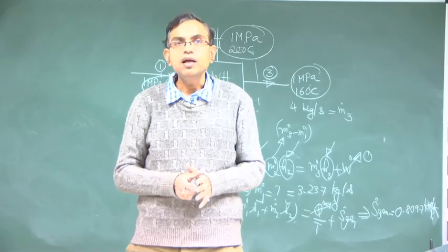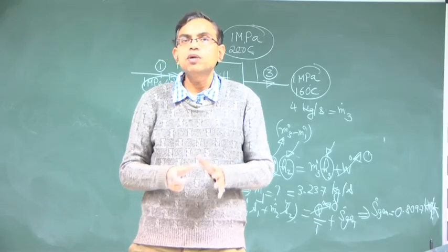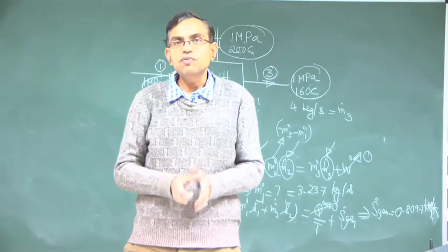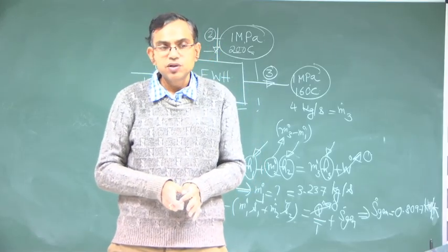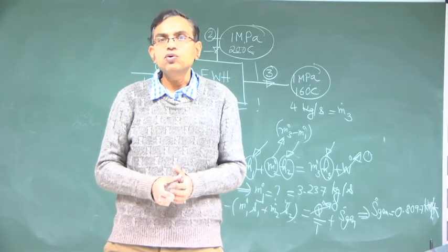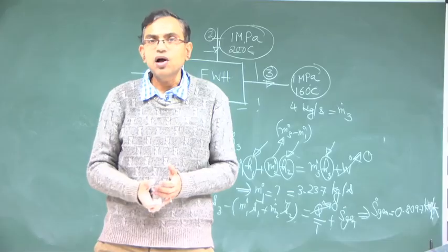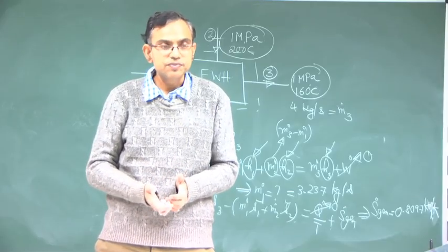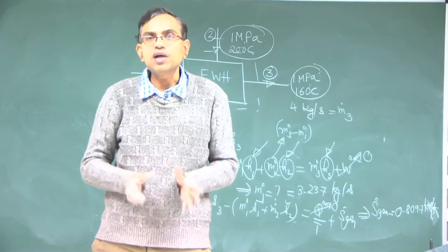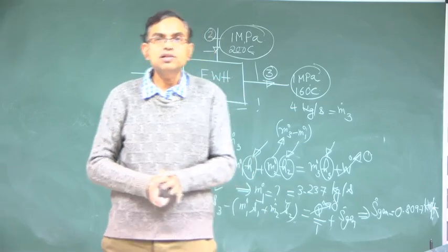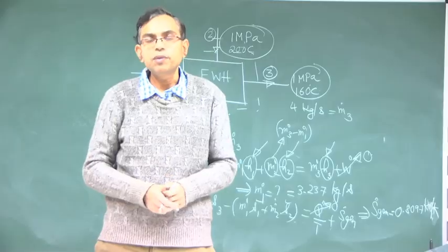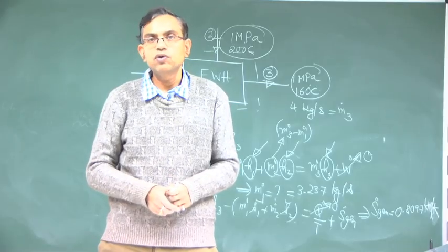That should be the message from the problem solving desk so far: for solving entropy transport problems, we commonly have to combine the first law and second law, sometimes along with the TdS relationship, and that gives a structure of the basic equations that you need to solve problems related to entropy transport across a control volume.